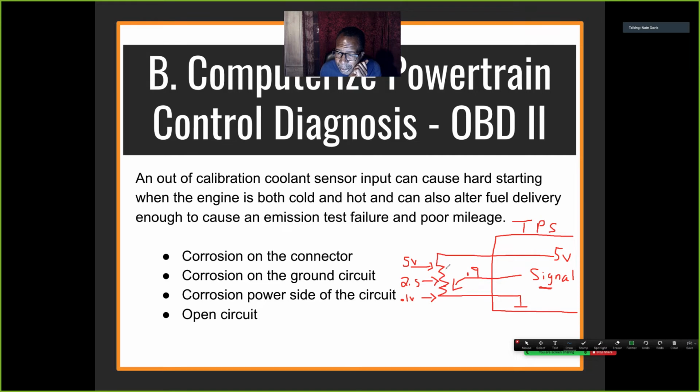If I'm up here and have all this resistance ahead of it, I require 4.5 volts to push the current to ground because I have to push it through all this resistance. If I'm in the middle, I have to push it through this resistance to ground. If I'm down here, I only need about 0.9 volts to push the current through the resistance to ground because that's normal. Now if I add resistance to it, I have the normal resistance plus this. That means I require more voltage or pressure to push the current to ground. So this number goes up. Gotcha.